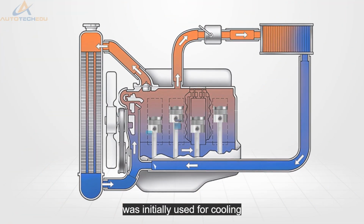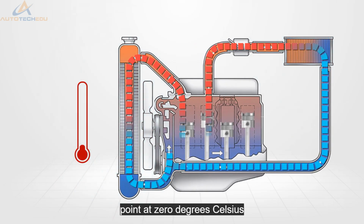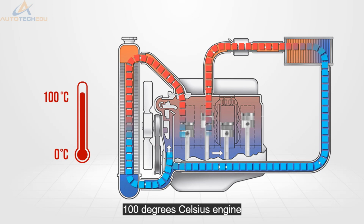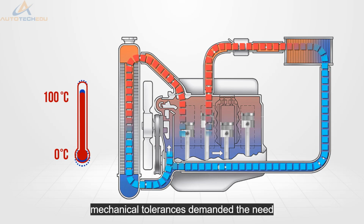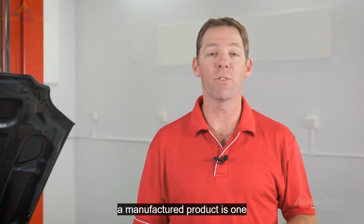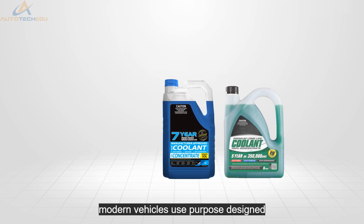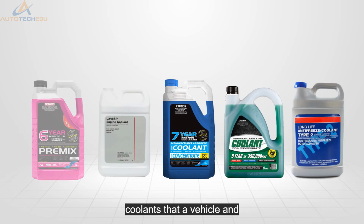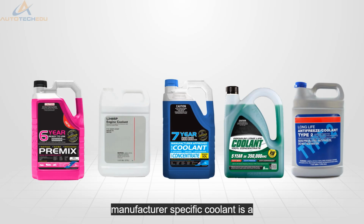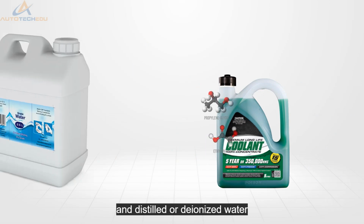Water was initially used for cooling an internal combustion engine, but due to its high freezing point at 0 degrees Celsius and low boiling point of 100 degrees Celsius, engine mechanical tolerances demanded the need for wider operating temperatures. Replacing water with a manufactured product is one way to achieve this. Modern vehicles use purpose-designed coolants that are vehicle and manufacturer specific. Coolant is a mixture of chemicals such as ethylene and propylene glycol and distilled or deionised water.